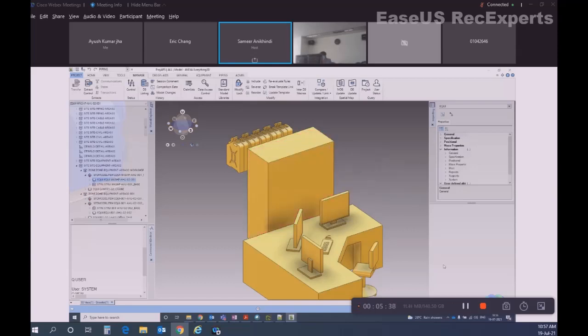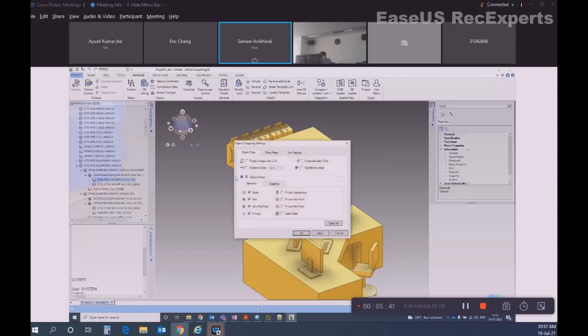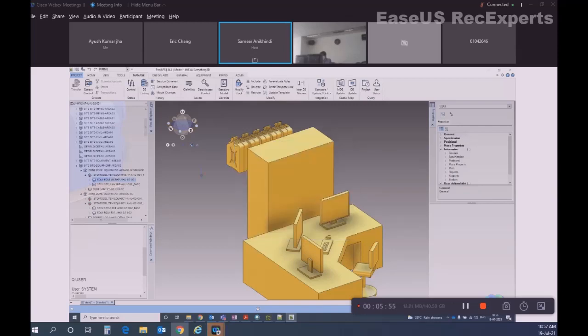So this is snapping. So here there are element snaps, and in graphics these are 2D snaps. As I told, endpoint, midpoint, nearest. Okay. So let me use the ID command. I'm using the ID command to demonstrate all the functionalities, but there are more commands also.